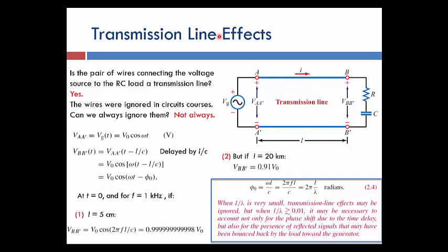So the effects of the transmission line: first, the attenuation, of course, even if it's just wire, because the transmission line is made of conductor, so it will have a specific amount of attenuation. Second, the delay. Third, the dispersion. And fourth, the reflection of the signal, or part of the signal, in the opposite direction.